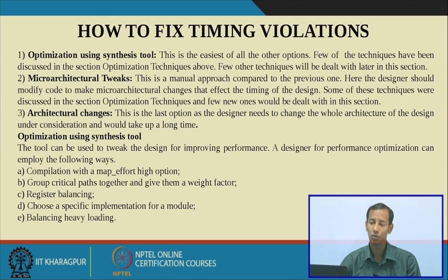There are several ways to do that. One way is optimization using the synthesis tool. Suppose one path is taking too much time, and that's why you are getting the setup time or hold time violation.